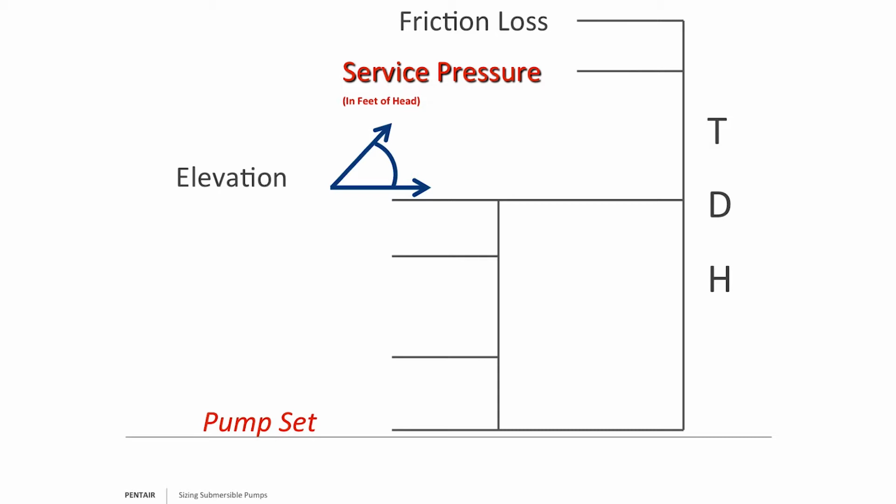if that was, say, 100 feet of elevation, where it's rising 100 feet, now my worst case, and here's the key words, I should say, is what is my worst case scenario? If I have one that's at 0 feet of elevation, but then the one on the top rises 100 feet of elevation, I must add that 100 feet of elevation in there. And then the one at 0 elevation, again, is not my concern. The installer might need to put in a pressure reducer valve, but he's the professional to do that. I don't worry about that.